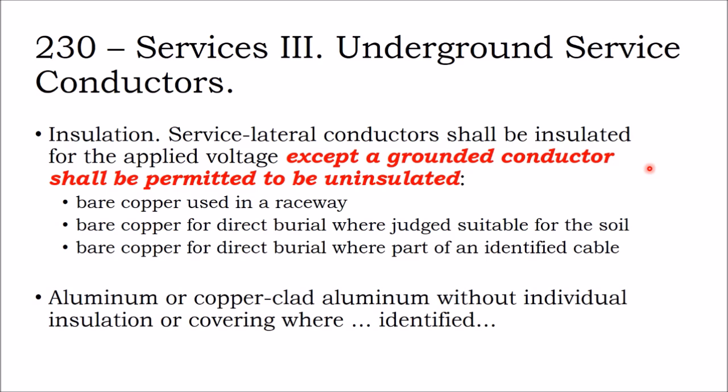But there is one conductor there whose job it is, not the neutral. The neutral's job is to provide a reference to ground. So the neutral is grounded, but it's not grounded all over the place. Then it wouldn't be a very good reference. It needs to be only grounded at one point. The utility, more often than not, is providing that point.